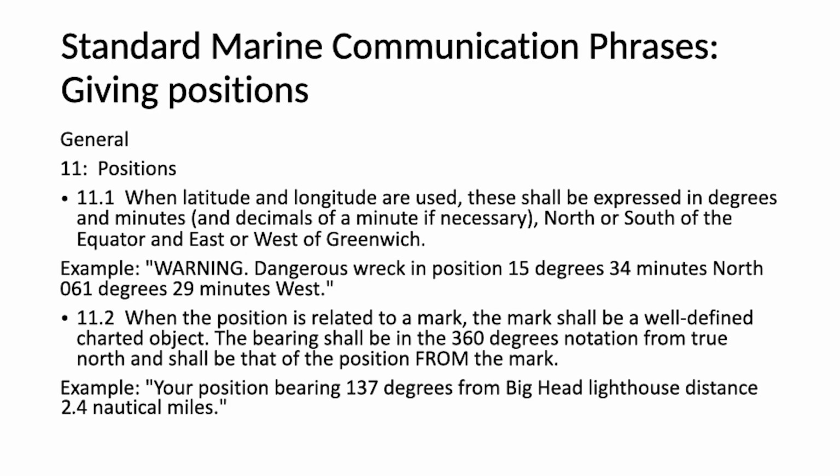Standard marine communication phrases. These are used when giving positions. When latitude and longitude are used, these shall be expressed in degrees and minutes, and decimals of a minute if necessary, north or south of the equator, and east or west of Greenwich. For example, warning, dangerous wreck in position 15 degrees, 34 minutes, north 061 degrees, 29 minutes west.